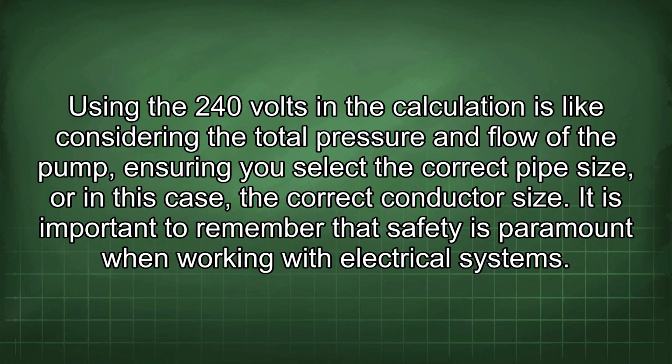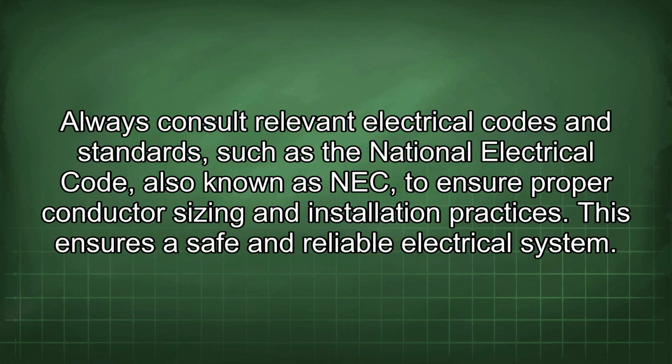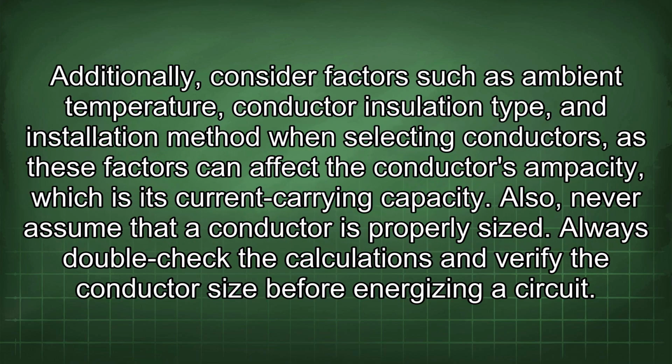It is important to remember that safety is paramount when working with electrical systems. Always consult relevant electrical codes and standards such as the National Electrical Code, also known as NEC, to ensure proper conductor sizing and installation practices. This ensures a safe and reliable electrical system. Additionally, consider factors such as ambient temperature, conductor insulation type, and installation method when selecting conductors, as these factors can affect the conductor's ampacity, which is its current carrying capacity.